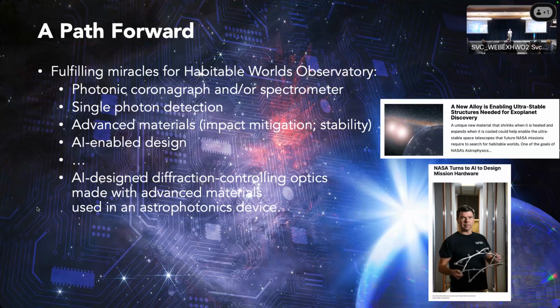And I've got a little example of a press release for an unrelated bit of NASA work. This is one of these newly engineered metals. It has a coefficient of thermal expansion that is designed to be basically the same as aluminum, except the sign is the other way. So that if you build this in concert with these two materials together, you can make things, with varieties of different metals, that always have near zero CTE for a reasonable temperature range.